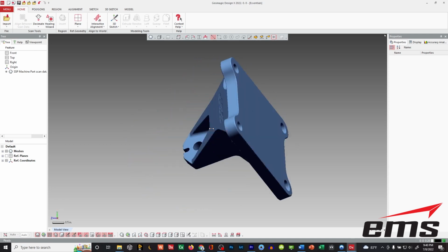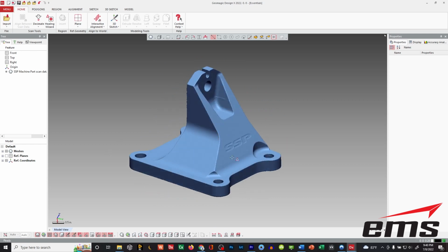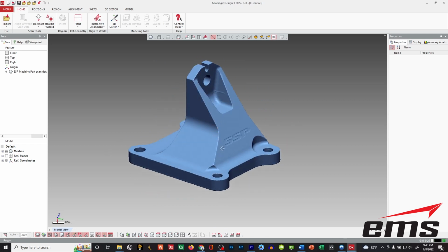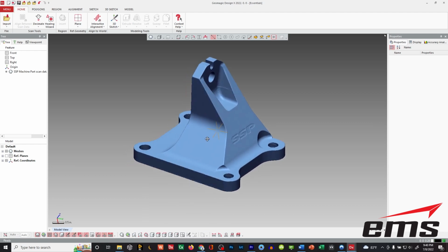If I go to the true top, side, front view, you can see that we didn't define a coordinate system when we scan. Now you can do that, or you can put it in one when you're done scanning, depending on the scanner and the scanning software, but we didn't do it. So we'll do it here. That's going to be the first thing. We want to get this so that we've got some nice views.